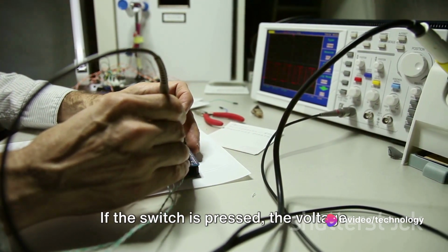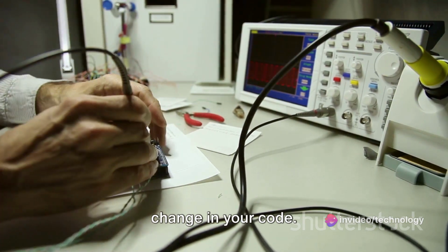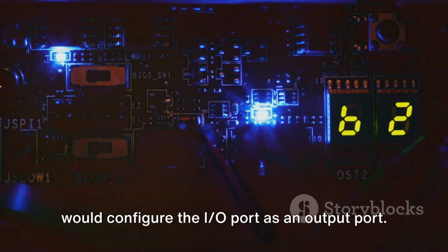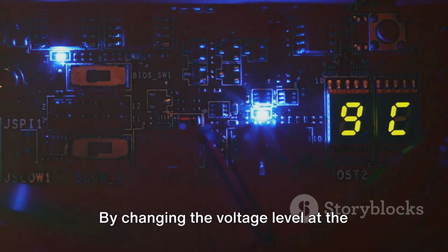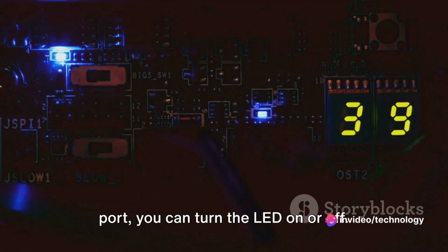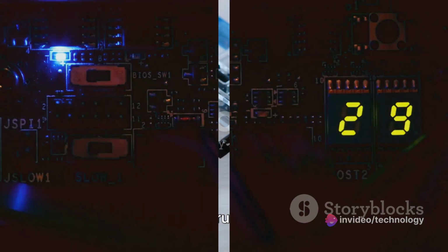If the switch is pressed, the voltage level changes, and you can detect this change in your code. On the other hand, to control an LED, you would configure the I/O port as an output port. By changing the voltage level at the port, you can turn the LED on or off. Well done! You can now handle I/O operations.